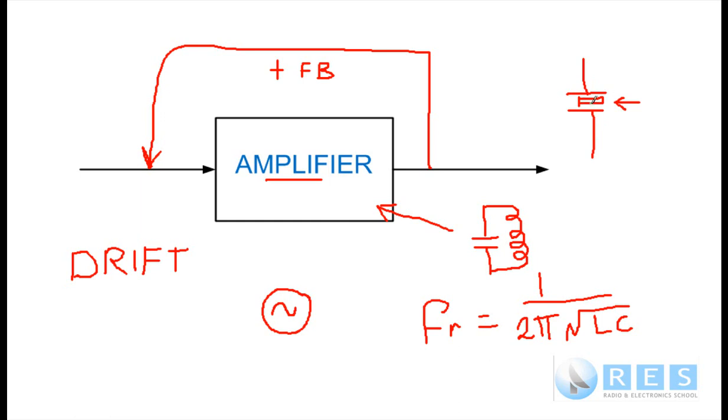We don't file it down with a bastard file. The way you adjust the size of a crystal to a particular frequency is to hone the quartz stone down like a jeweler would, using very fine abrasive materials.